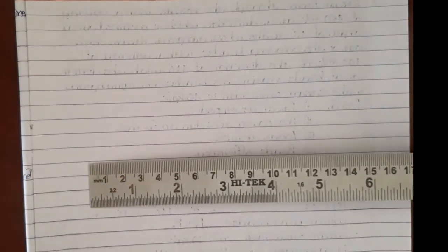So before solving this problem, as I urged you in the last class, please have an understanding and familiarity with the combined velocity triangle for the impulse turbine, which we did use in our derivation. Okay. So based on that, let me start solving this. Generally we will have U as the base for both inlet and outlet triangles, right? The combined triangle will have U as the base.